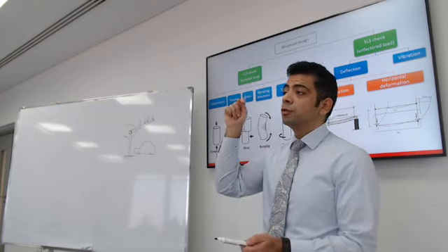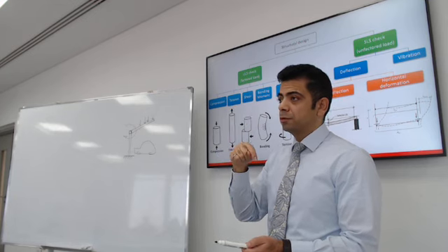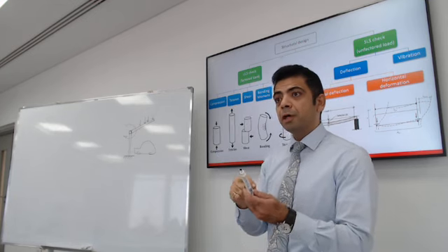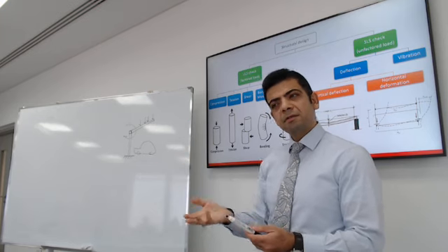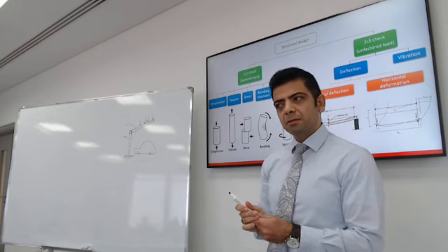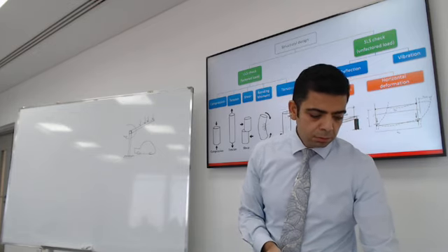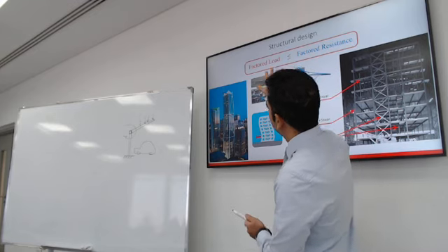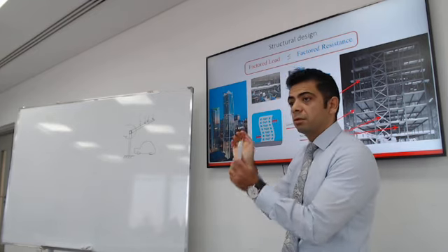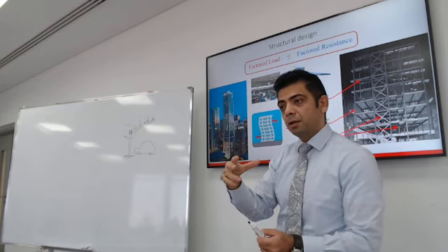To compare it to the actual load. So you calculate the load on the beam and make sure that you choose a section that has a capacity that is bigger. Does that make sense? Yes. No? I want the resistance to be bigger than the load. The resistance of the section to be bigger than the load.